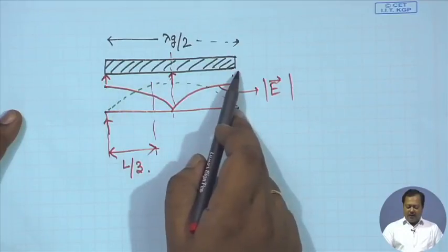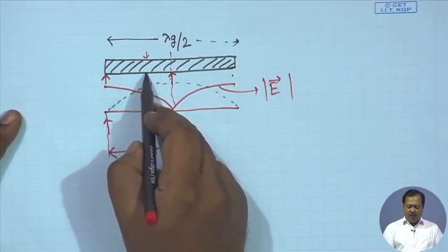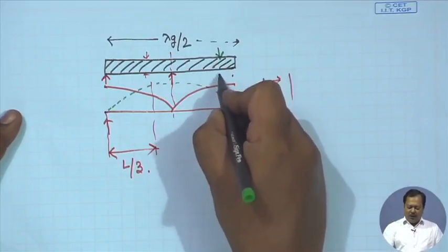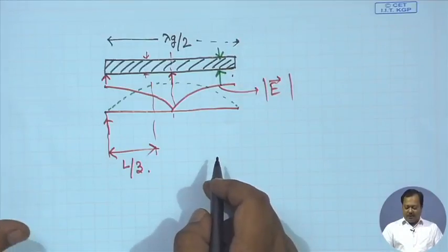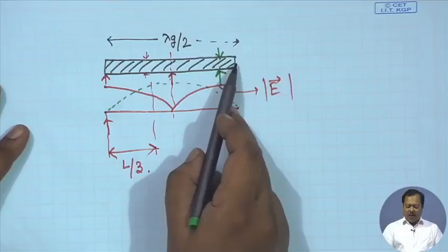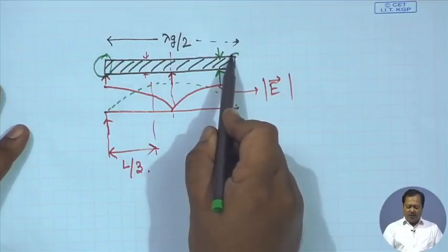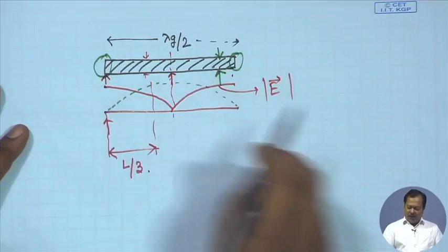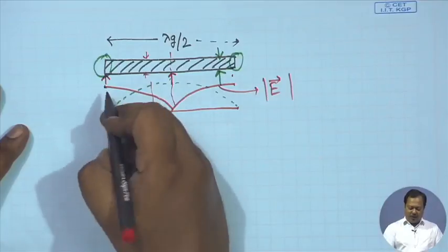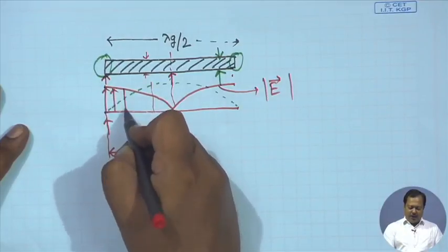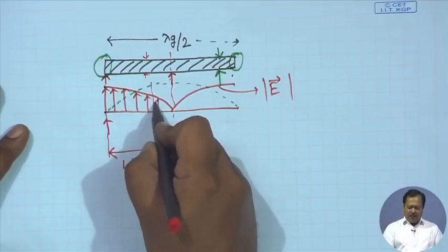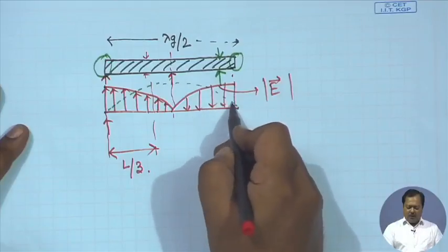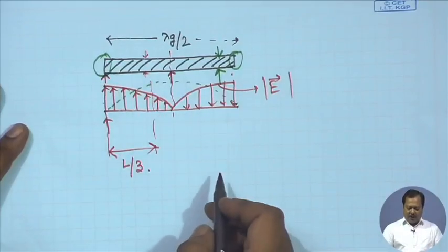This resonator, when its width is very small, will not radiate, but if we keep on increasing the width of the resonator, it starts radiating, and this radiation comes from the fringing field at these two sides. If I look at the fringing field plot, this is the direction of the electric field. I did not show it in this diagram. Since it is radiating, if on the left hand side it is upward, here it will be downward, and at the end we have fringing field.